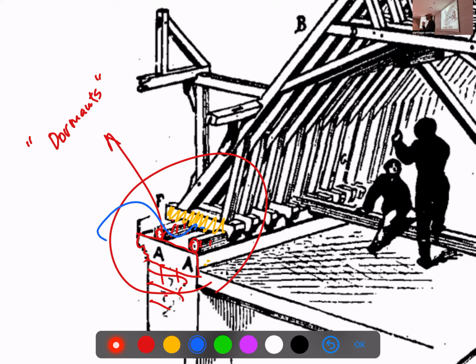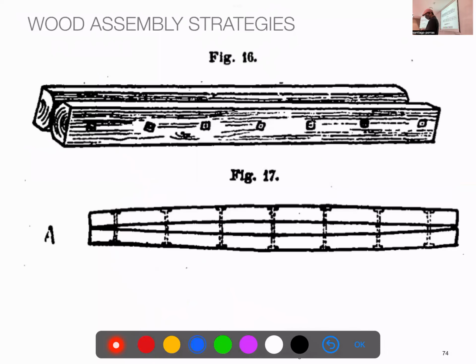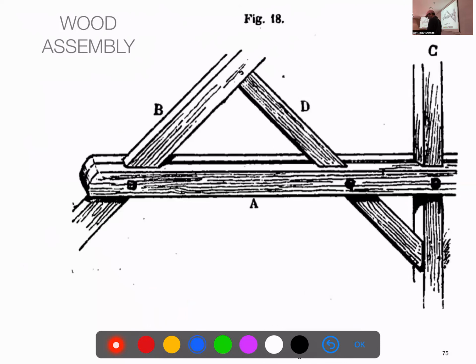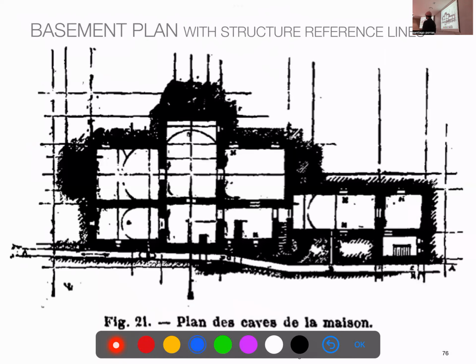Always when we use timber for interiors, for structure, we try to isolate it from fabric, from bricks, from concrete, so the humidity will not affect it so much. The second is to have this kind of long element just to cover the thickness of the wall, right? Always the wooden structures in those buildings have some kind of device to adapt to that wall thickness. These are tricks to counteract the deformations we saw before when making the construction, and tricks to have a structure that is easy to build but well designed. Then, this is like the basics to understand how buildings are made.